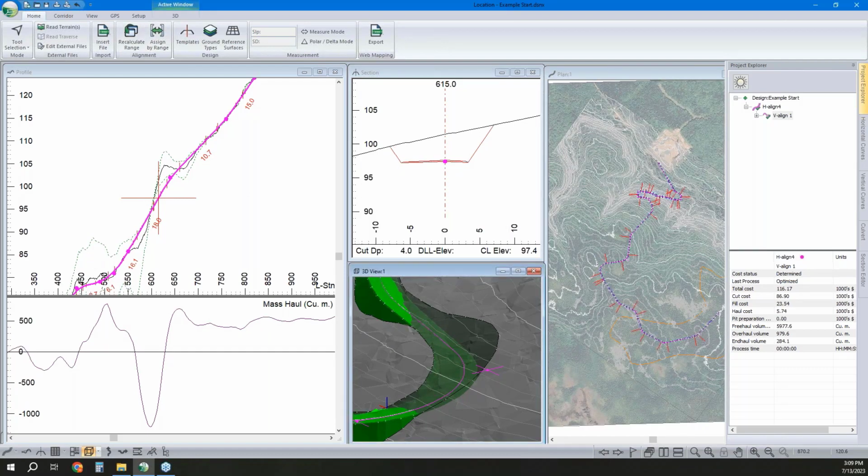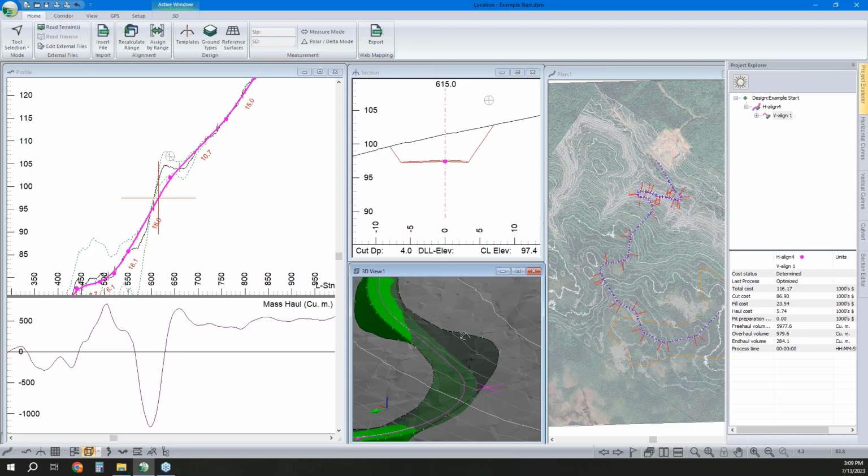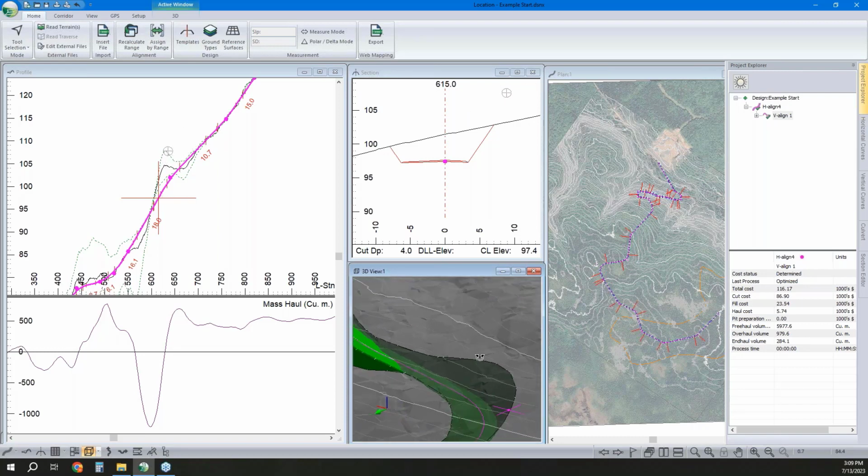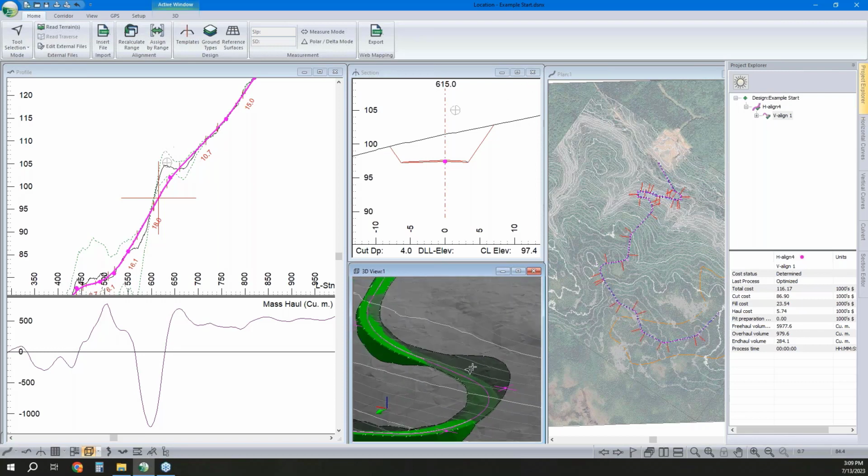So the next thing on our list of things to consider is, well, we've got this crown that's going to help push water off to the side, but we need somewhere for it to go once it gets to the side, or at least somewhere to store that water. So the next thing, real obvious thing to tackle, is ditches. And aside from just taking the water off our road top, they also give us capacity to intercept overland flow or subsurface flow from upslope.